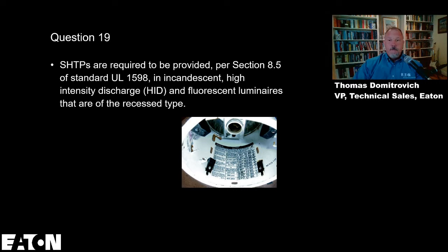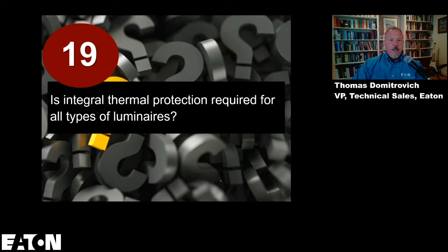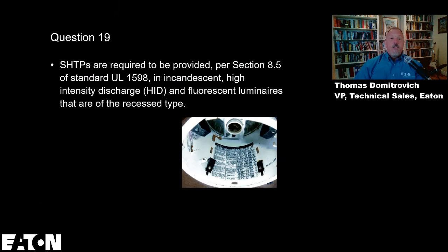Alrighty then. And let's take a look back at that question, make sure I answered. Is integral thermal protection required for all types of luminaires? And the answer to that is no, it is not. It is required per the standard for HID, fluorescent, and incandescent.